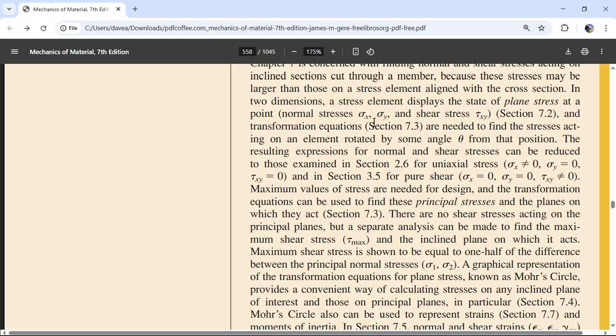So we have plane stress. That means we're not going to have stresses in 3 dimensions. Plane stress is not just normal, not just tension and compression stresses. That's probably where I would make a mistake and be like, oh, we just have plane stress, right? I don't have to deal with shear stress. No, you do. But things are just being pulled apart in this direction, compressed in this direction, or vice versa, and they're being stretched in a diamond shape, but all that is happening along a 2D surface, not in the Z direction.